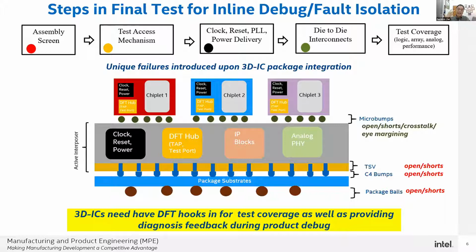That's number one. The second thing, at the die level, your probing solution will change completely when you go to hybrid bonding. The probing that you do for microbump will not apply to hybrid bonding. So I believe there is industry work happening as we speak to address this.